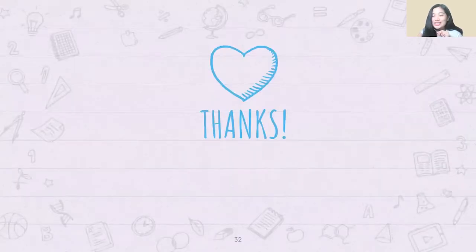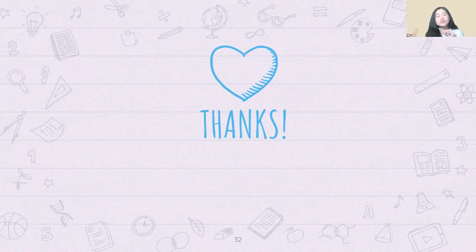Okay, so that will be the end of our lesson for today. Okay, guys, our lesson for today, just to emphasize the Kron reduction method. And the Kron reduction method is just basically eliminating, for example, the n by n matrix to a smaller n by n matrix. So 4x4 to 2x2, and always remember to have at least a stock knowledge or a previous knowledge of our Y-bus admittance matrix to be able to come up with an easier step to follow the process of our Kron reduction method.